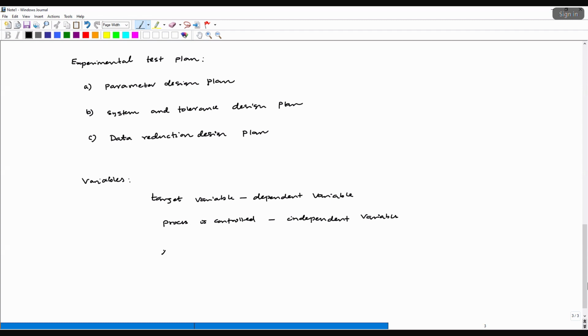For example, let's say I have a pipe and I am flowing some water through it, and I want to measure the pressure. So we know that the pressure difference delta P, if it is a circular pipe, I can write it as 128 into mu L divided by pi into diameter to the power 4, into the flow rate.